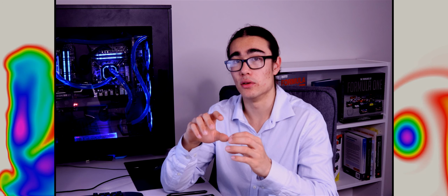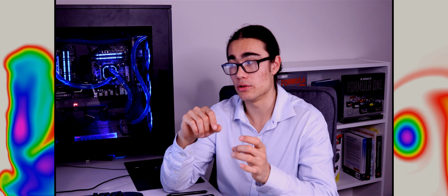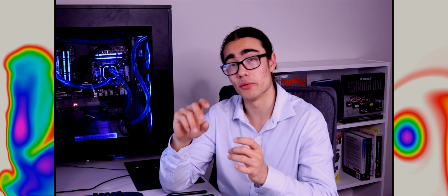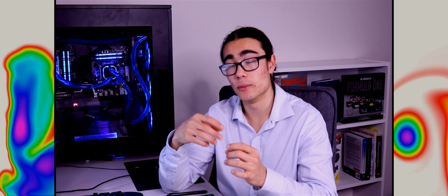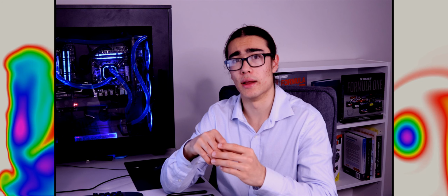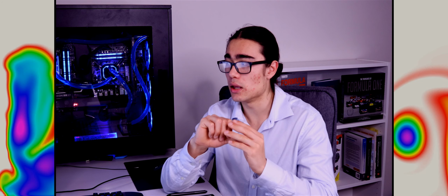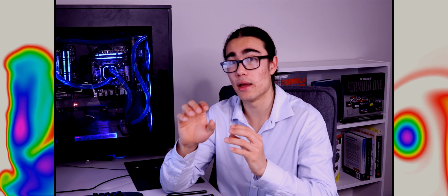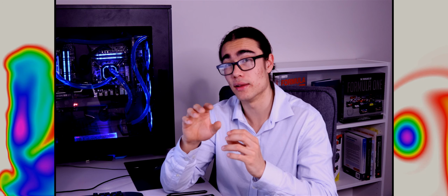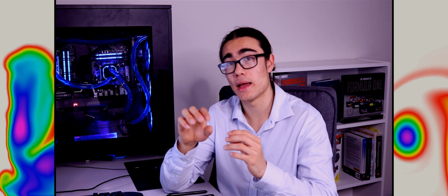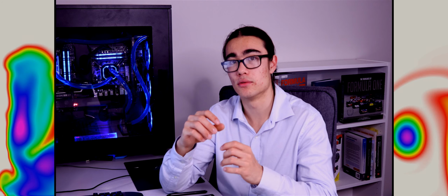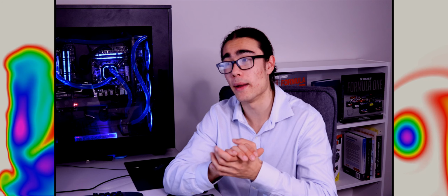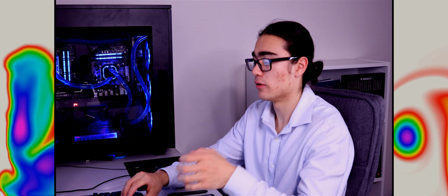Now I've rotated it in such a way to increase the performance of the airfoil in this case. The primary objective of this study was to see if we could use the Magnus effect on a leading edge application to reduce the separation and thereby be able to run an airfoil at a greater angle of attack. Now, in this case, I've actually pushed the airfoils at 8 degrees angle of attack, and I've done that so that we can begin to see a bit of the separation out of the trailing edge, and then we can generally see if there's an improvement with the Magnus effect. So let's have a quick look at the results.